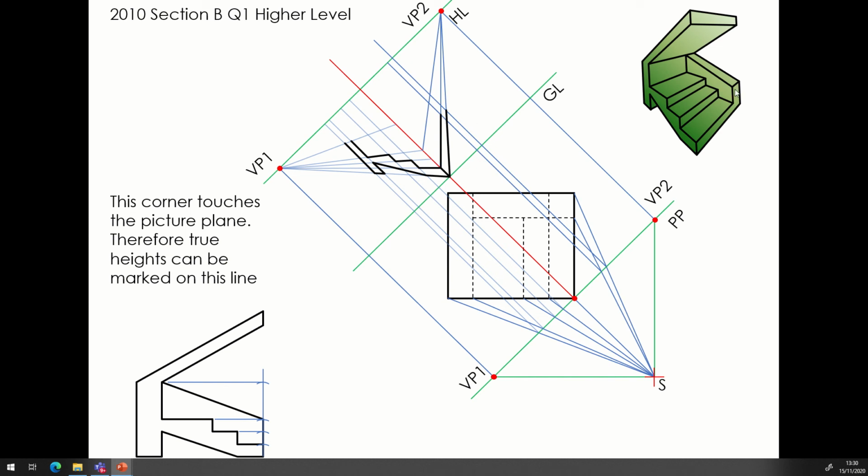It's going to go up to our height here before it takes this slope back. So we have our height measured on our measuring post here, and we bring it across to give us our height there. And then we can just square that around, and that's our plinth.